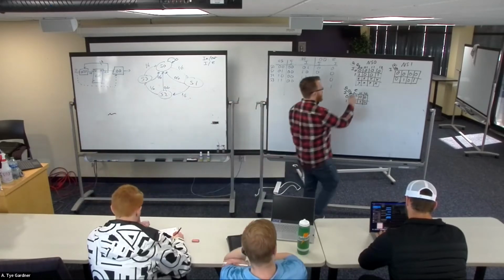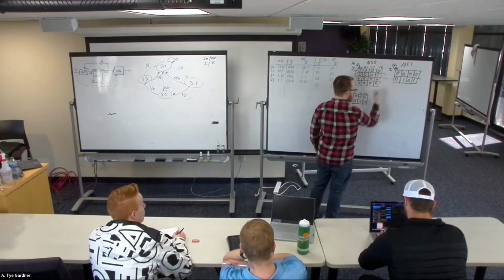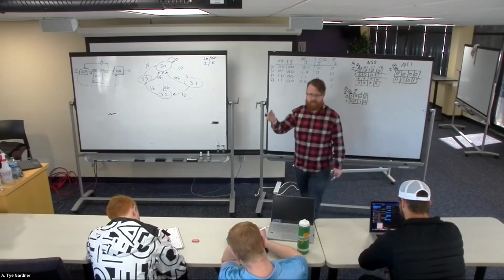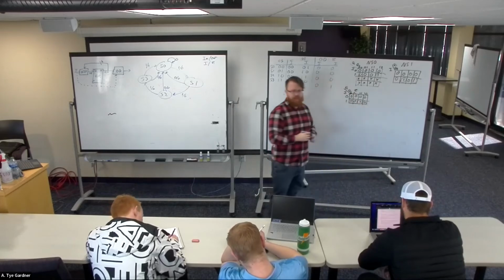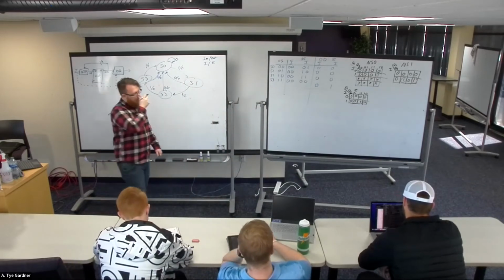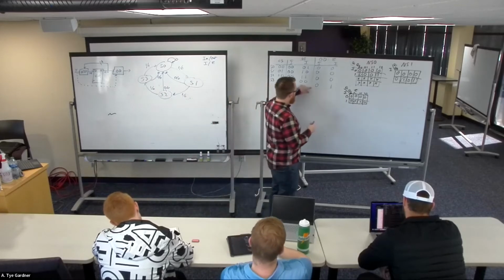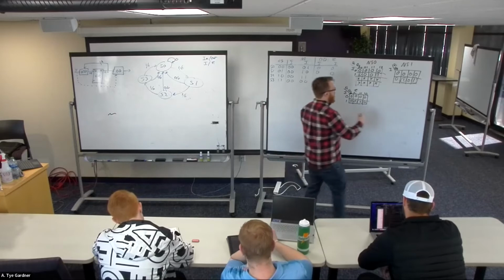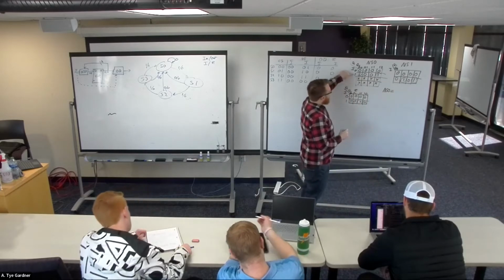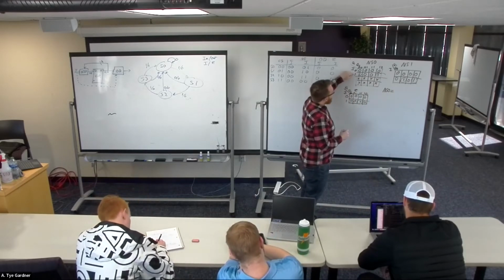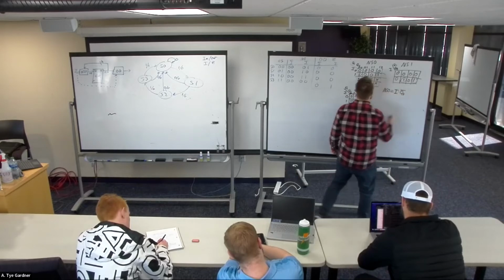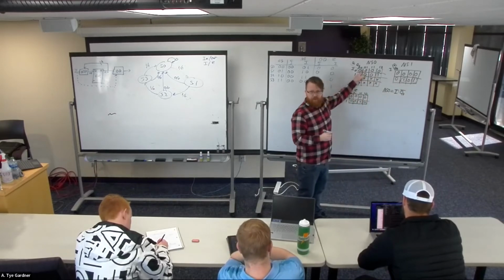We go to our K-maps and we recognize that we're wrapping around. Oh, this is blue. And this K-map just has 2 on its own. They're not adjacent. They can't simplify. This one has 1 on its own. Can't simplify. And now I can say things like my NS0 is equal to I and not Q0. Right, because the Q0 doesn't change as it wraps around.